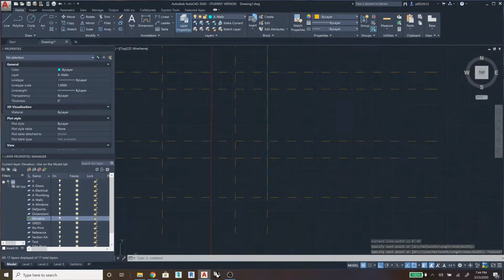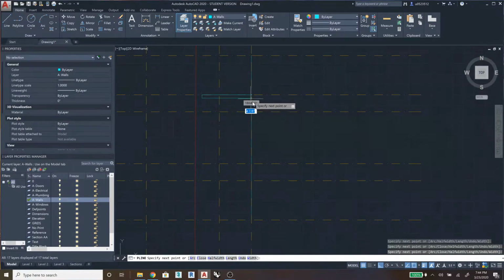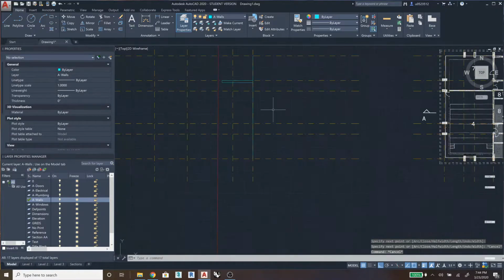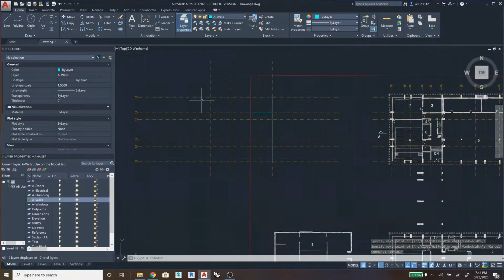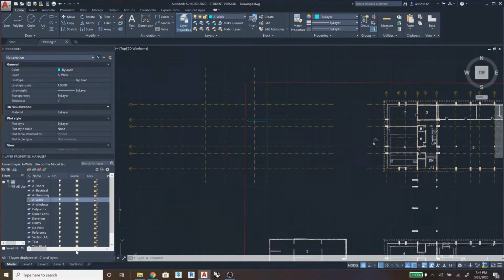If you go to your walls, you can start modeling elements like you've done. So once you get this grid going and this view going, you notice I'm modeling sideways. So up is to the left and down toward the ground is to my right. That might be a little confusing, so we're going to set up our viewport, and you can actually model in model space on your layout instead, which would be upright if that makes more sense to you.